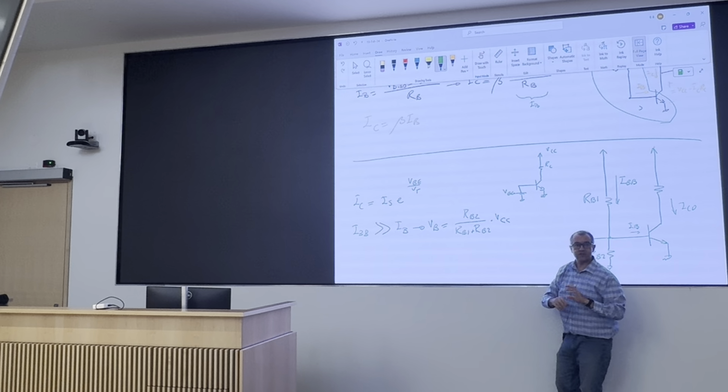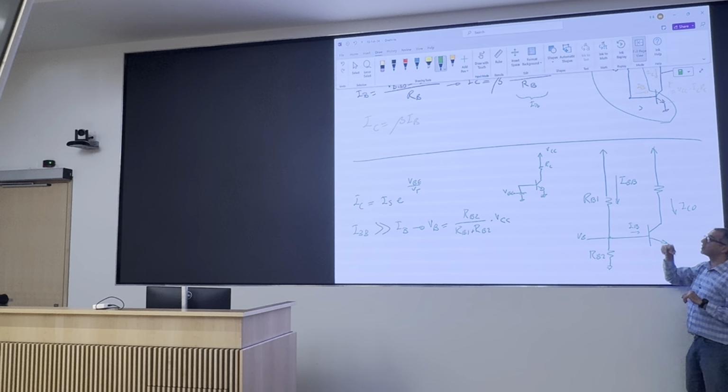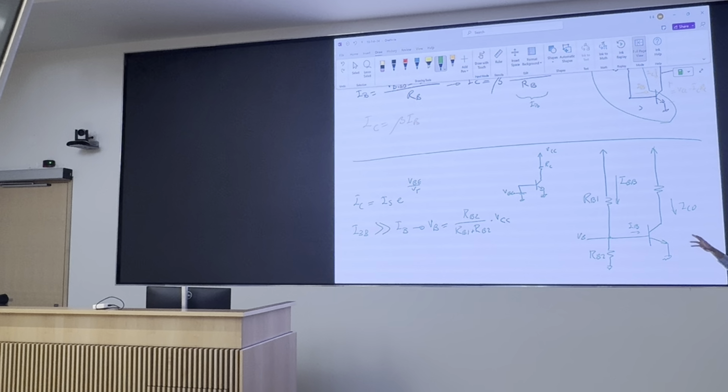You go and make the circuit, you call your boss in, you turn on the power supply and your device starts smoking. Why? Because as soon as you turn this on, it warms up a tiny bit. Let's say the temperature of the device goes up by 2 degrees. 2 degrees means that VBE on for a given current would be 4 millivolts less, but you fixed the voltage. So it has to be at 0.72 volts.